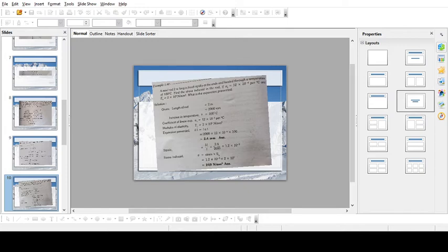Okay. So given that a steel bar has 6 into 10 to the power 3 mm square cross sectional area. So it is given in terms of its area, that is, area of steel AS is equal to 6 into 10 to the power 3 mm square. It is fixed to a copper bar whose area of copper AC is equal to 4 into 10 to the power 3 mm square. Given that both are of the same length, that is L1 is equal to L2, that is 1.5 meters. So you can write it in mm, 1.5 into 10 to the power 3 mm.